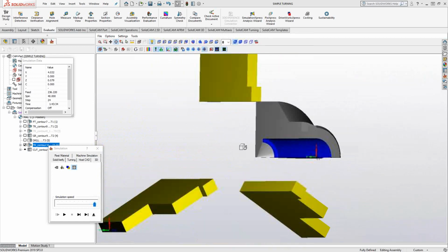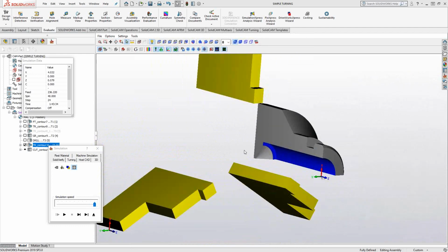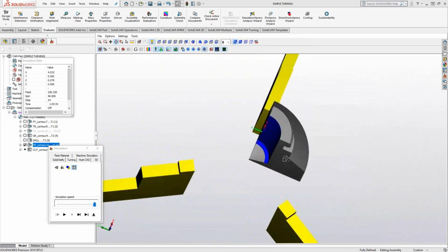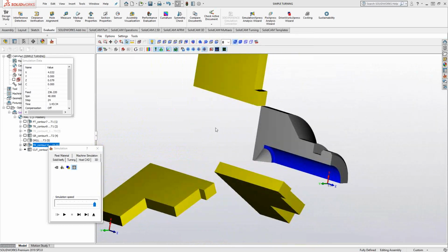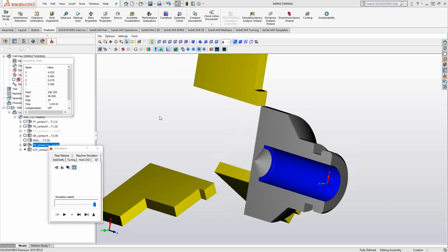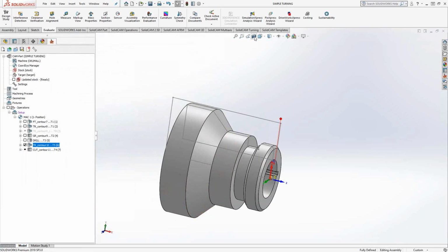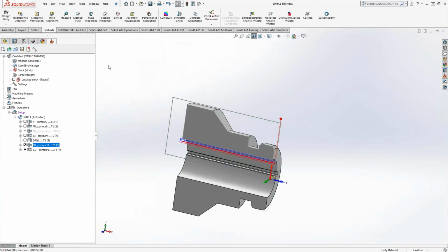And again, this is only available in the lathe view, so that's why it makes sense to look at it in terms of 3/4, half, or single quarter, only because as turning, we really just want to see what that thing looks like from these angles, where there's not going to be much of a difference in turning toolpath. Now this half cut is similar to what you would have gotten inside SolidWorks, where you can do this section cut. The same sort of idea. So you can see the halfway through.